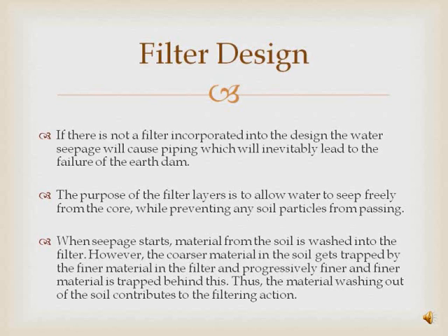When seepage starts, material from the soil is washed into the filter. However, the coarser material in the soil gets trapped by the finer material in the filter, and progressively finer and finer material is trapped behind this. Thus, the material washing out of the soil contributes to the filtering action.